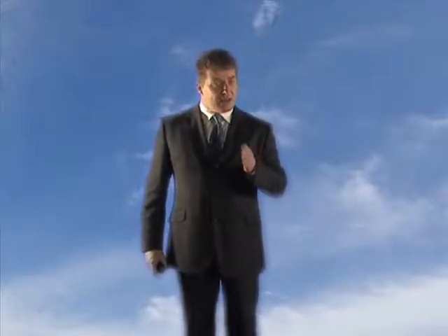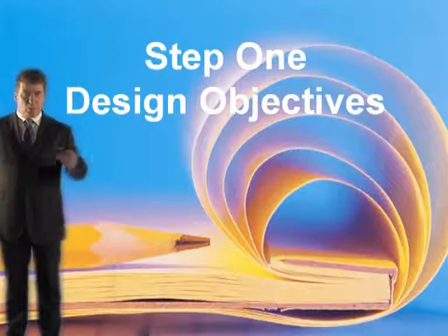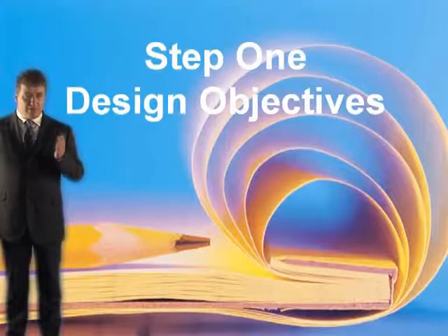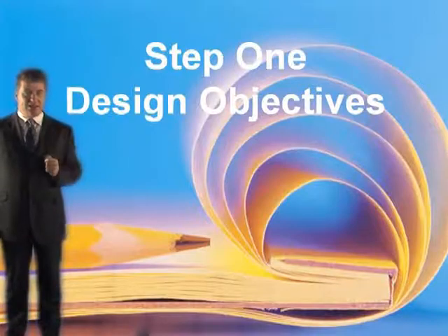Now the best way to carry out this check is to check the scheme using the 11-step guide, and when a step is not applicable, we just ignore it. So you can still use the 11-step guide. Step 1, the design objectives. Well, these are specified as life safety. In other words, you've got to extract the smoke from the shop unit using a reservoir before it can enter the atrium. So that's the design objective.